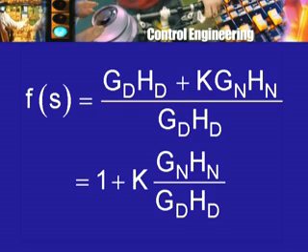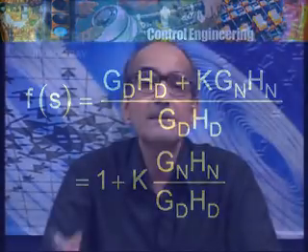So, suppose I choose a suitable contour in the S plane, apply Cauchy principle of the argument for this function f, then will I get the information that I want? What is the location of the roots of this characteristic polynomial? Or in particular, I want to make sure the system is stable, so there should not be any roots in the right half of the complex plane nor on the j omega axis.